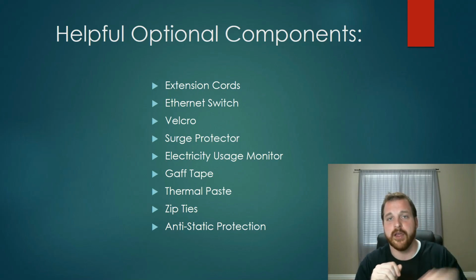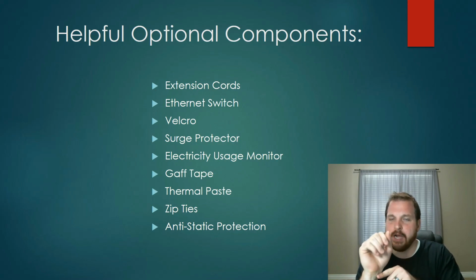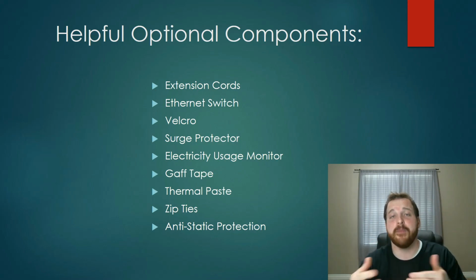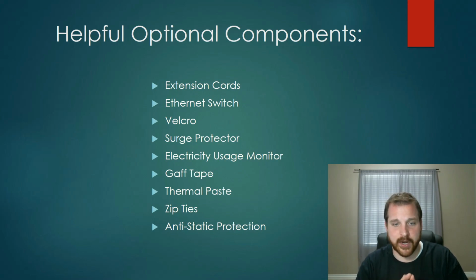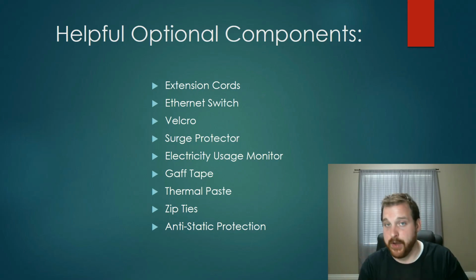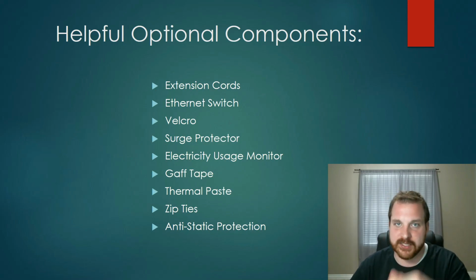There's a wristband, and then it's got a wire attached to it that you can just clip to a ground, and I just clipped that to the frame, seeing as I was working on a non-static surface anyway. I'd recommend getting something like that so you're not shorting any of your equipment while you're trying to build it. That would not be a good thing. So make sure you've got something to protect yourself and your investment there.